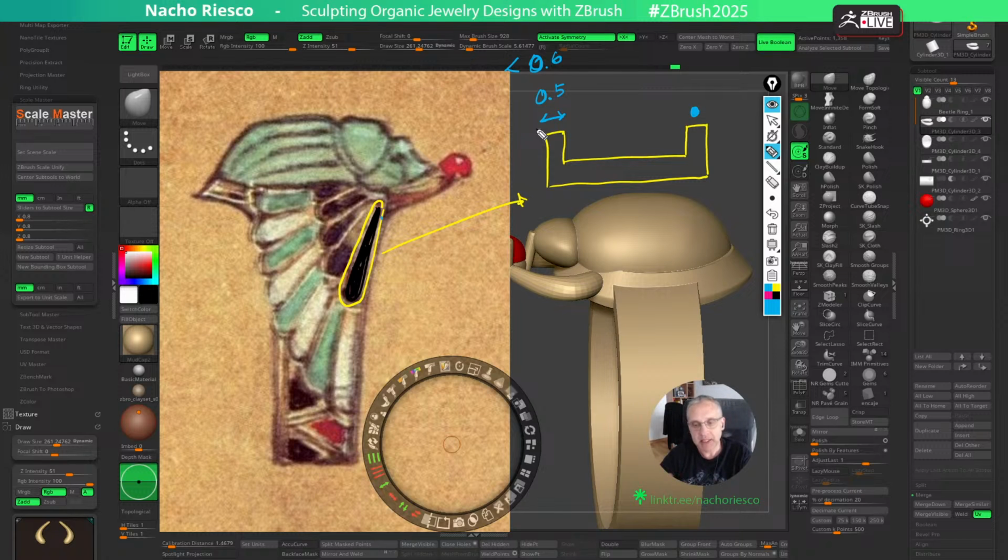Once we have the metal, and we have 0.6 here, with manual tools we can start grinding and removing material until getting probably 0.4. The objective is to make it as thin as possible, but for getting a 0.4 thickness of the frame, I'm talking about this distance, it's a better idea to give it 0.6 or even more if we can, because we are going to get the final thickness during the manual processes.